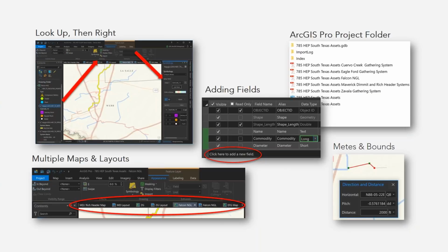Another small but certainly helpful feature my team finds is the ability to add fields when you want them. Instead of just tacking them on to the end of an attribute table, you can do this during an edit session. You can drag and drop exactly where you want them to show up within the attribute table.